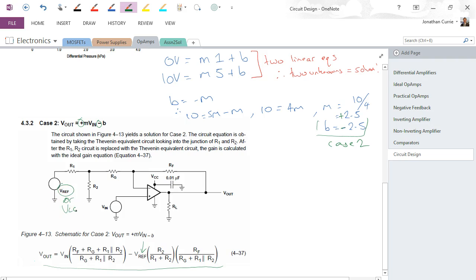It doesn't have to be a separate voltage, but if you've got one available, it can make the circuit design a little easier. And so we see we've got, with this solution circuit, 4 resistors that we have to solve for. R1 and R2, which is a divider on the reference voltage, which provides our bias, and RG and RF, which are our normal, and you'll see it, our input applies to the non-inverting terminal, so this is a non-inverting amplifier, which makes sense because we have a positive gradient, so we're at positive amplification.